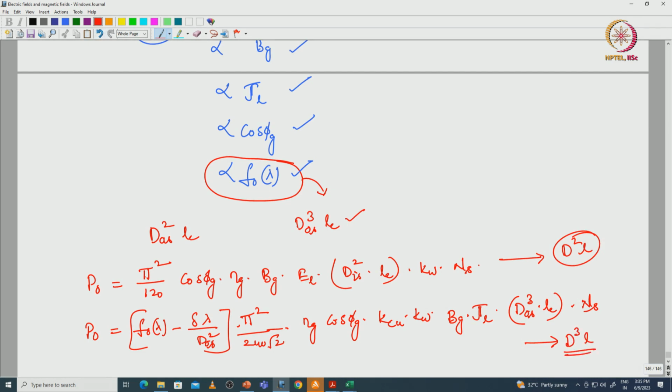Okay. These two sizing equations we can utilize for designing any machine with respect to the dimensions. If you want to calculate the dimensions of the stator with respect to the inner diameter and length of the core, we can utilize the first equation. If we want the stator geometry completely, we can see here stator lamination, where we require the inner diameter, outer diameter and slot area and slot dimensions and flux densities at the different parts of the iron. If we want to consider that, then we have to go ahead with the D cube L product equation.